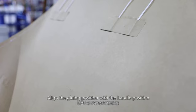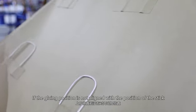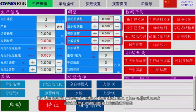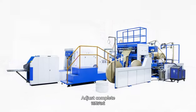Align the gluing position with the handle position. If the gluing position is not aligned with the position of the handle, go to the touch screen to adjust the handle and glue adjustment until it's aligned. Adjust complete.